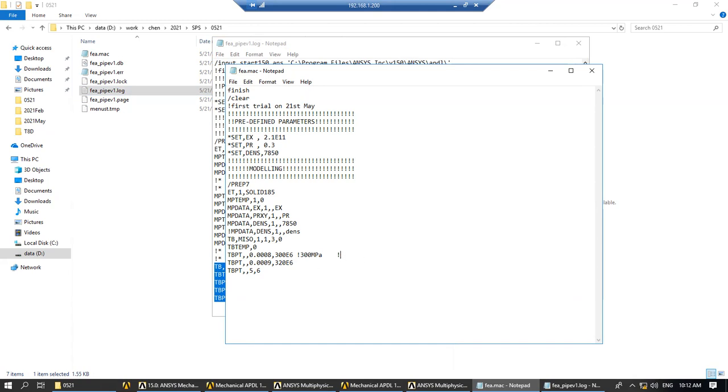The first stress over the first strain has to be equal to the material property of the Young's modulus. Okay, if you know the mechanical material engineering part, in this stress strain curve, the linear part or the slope or the gradient of the first linear part has to be equal to the Young's modulus of the material.